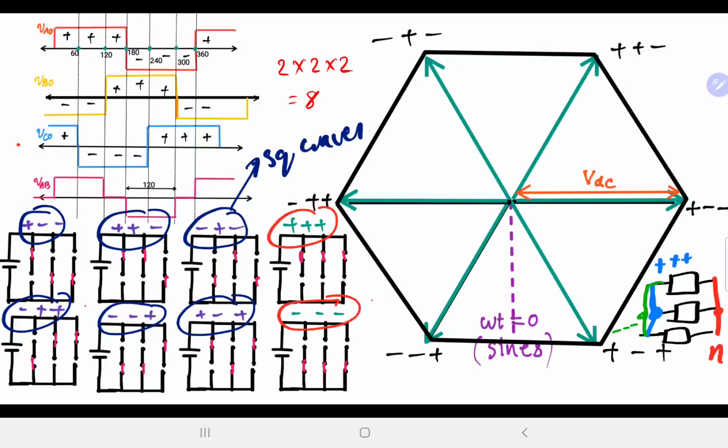So either way, both ends of the loads are short circuited with respect to each other, and that isolates the input side from the output side, and there is no power delivery from the DC link source to the output side, and therefore this is what we call the freewheeling mode, freewheeling switching states. Okay, so these two switching states are sometimes called zero vector or zero switching states.